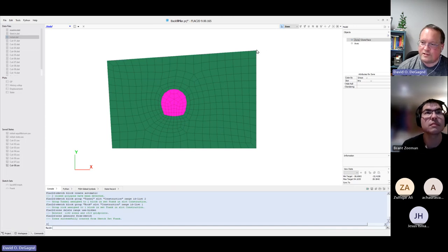Again, these aren't really the boundaries that you would want to have, but we've got some nice tools now in the model pane, which we're in now, where we can essentially automate the boundary conditions. It doesn't actually specify what the conditions are, but it lets us group them. So this would automatically get named to like west, north, east, south, I guess. And then it would try to do the same thing to the internal boundaries. So it might be like west 1, west 2, just depends on the angle that's involved.